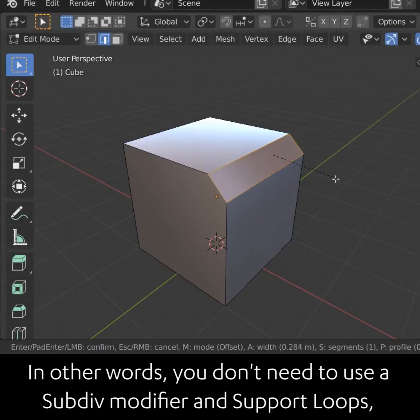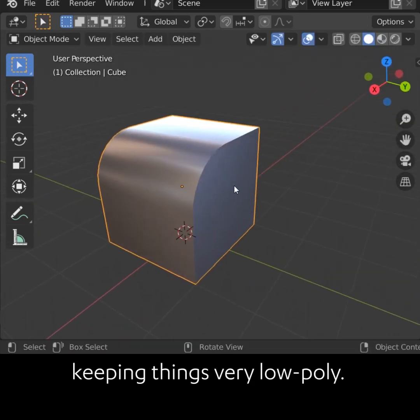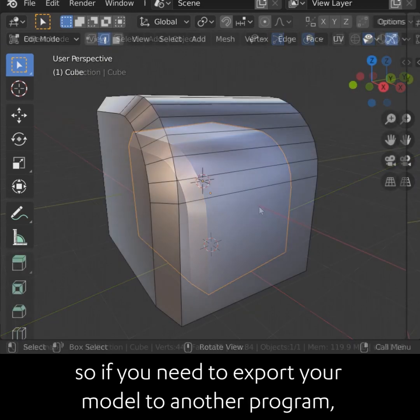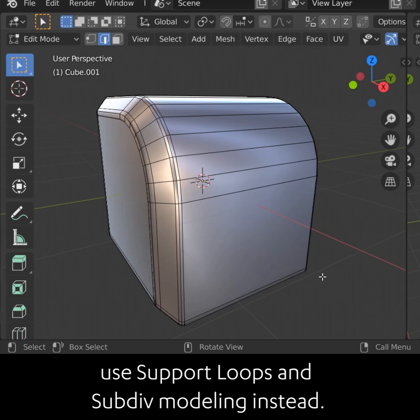In other words, you don't need to use a Subdiv modifier in support loops, keeping things very low poly. It's an efficient and fast modeling technique for objects that don't deform. Keep in mind, this only works inside of Blender. So if you need to export your model to another program, use support loops and Subdiv modeling instead.